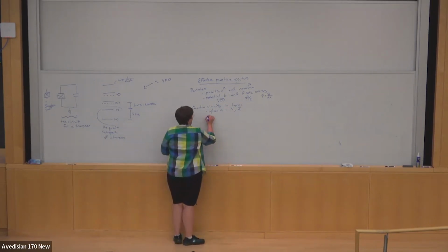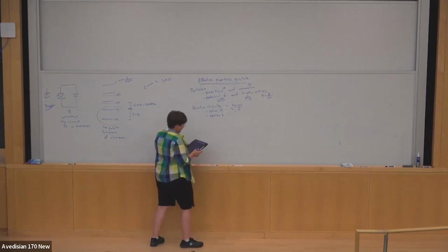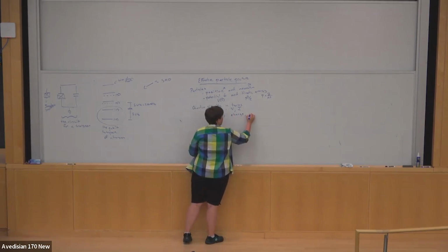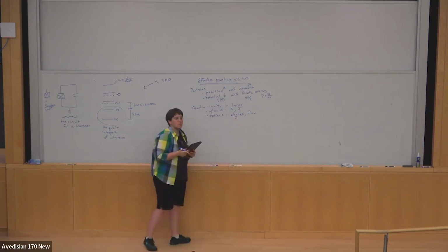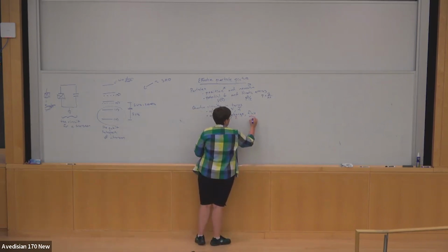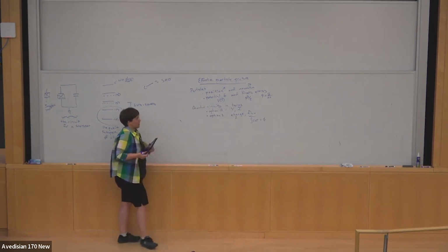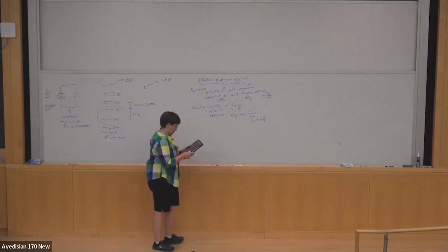What turns out to be more common in the quantum circuits, I think largely motivated by the math for the Josephson junction, is you write it in terms of charge and flux. So the number of Cooper pairs and the integral of V dt, which is phi. And so those are actually going to be the canonical variables that you use to define an effective picture.